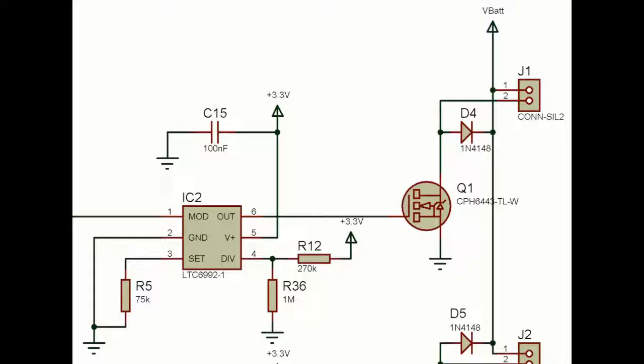The next part of the circuit is a voltage to PWM signal controller. I can input a voltage from 0 to 1 volts, which I've scaled correctly using the previous circuitry, and this outputs a 0% to 100% PWM signal, which I then use to power a MOSFET transistor and power the motors.